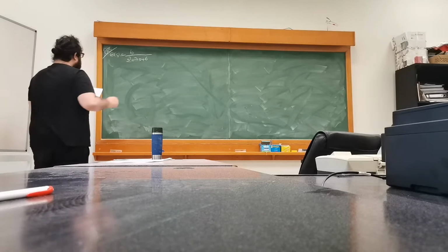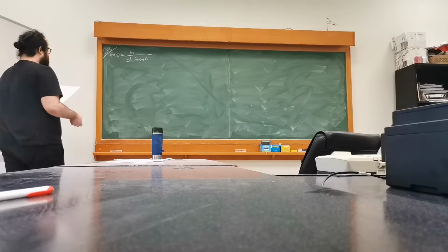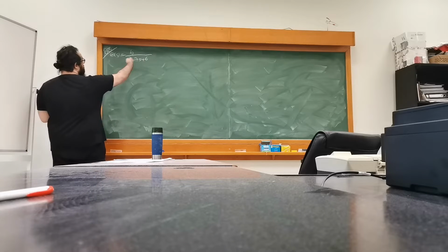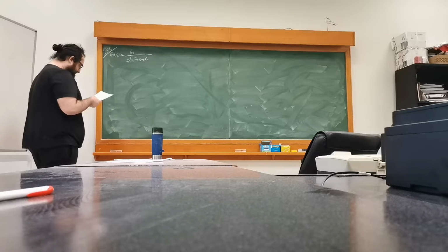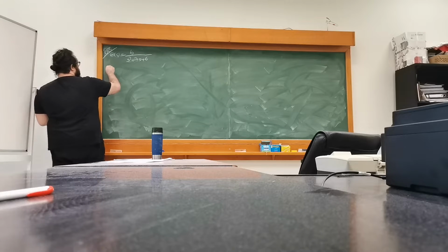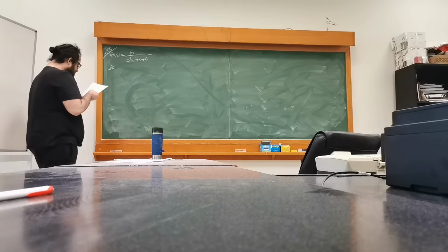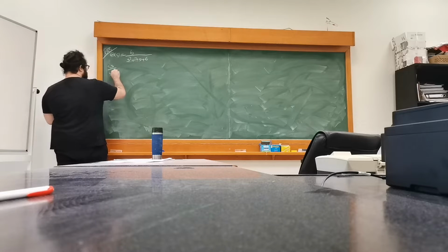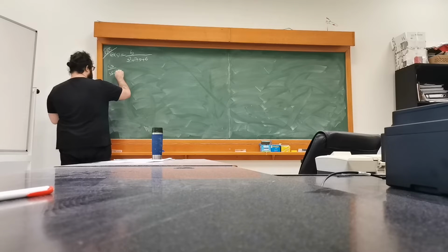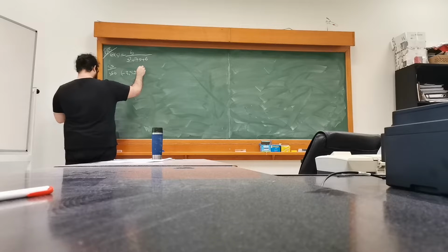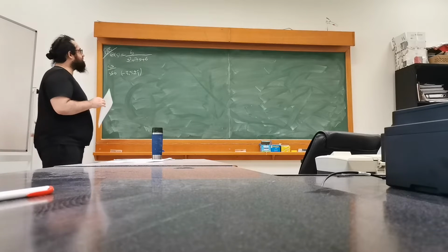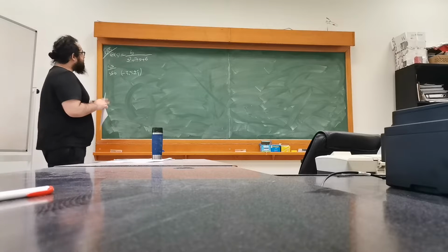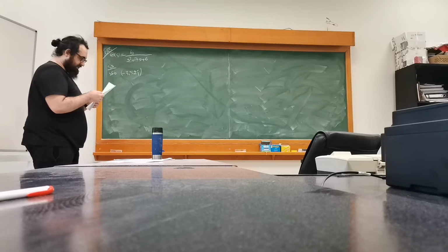So now, this is question 8, and here we again have sort of the same coefficients. But an integrator is missing because we are looking at a state space question here. So the first step is to acquire the state space model, and then the second part will be to design a state feedback controller that assigns the poles at 3.5 plus minus j. So we will first acquire the state space model, and then design a state feedback controller that assigns these poles for the closed loop.